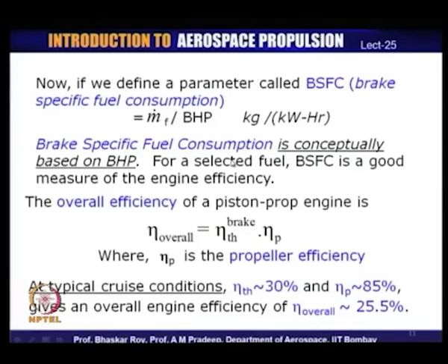Now, brake specific fuel consumption is conceptually based on the BHP. Conceptually, you can again have an indicated specific fuel consumption, where instead of BHP you use IHP, but as I mentioned, the more useful one is the brake specific fuel consumption. So, when we say BSFC, we are talking about the utility of the fuel in terms of the brake horsepower, the final horsepower that is available from the engine.